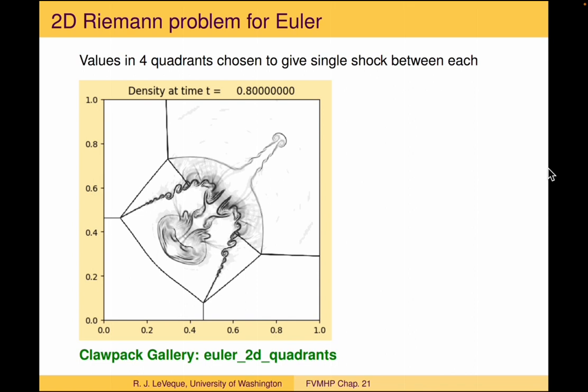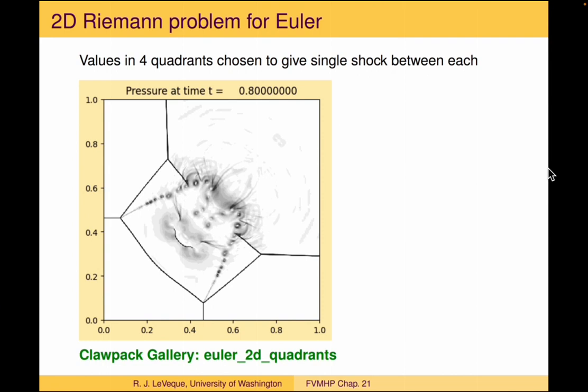But that's, in this case, sort of a numerical artifact, and it depends very much on which limiter you use, for example, how much and how fine a grid you use, exactly what sort of structures you get in these sorts of solutions. Also, when you look at the pressure, the pressure should be identically constant along that line, but you can see low pressure regions in the centers of these vortices that have formed where the pressure is lower than it should be because of the swirling flow.